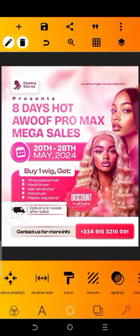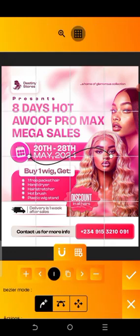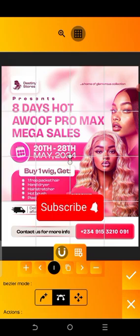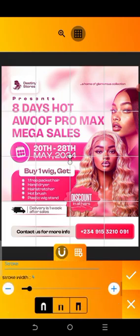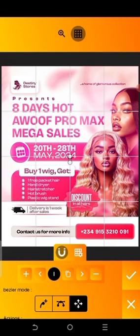And the next thing to do is we're going to go to where we have the bezier. Click on the gradient, move to the second bezier mode, then move it down to this place. Make sure that the magnet is turned on. Move it here. This is how I create my straight line. I don't use shapes. And this as well. Move it here. But this is too long, so I'm going to move this point down to this part. Yeah, good. And this one too, I'll move it to this point. Then make sure that the stroke width is not too much. 2 is okay. Click on the third bezier mode, then move it down to around this part, then check mark it.